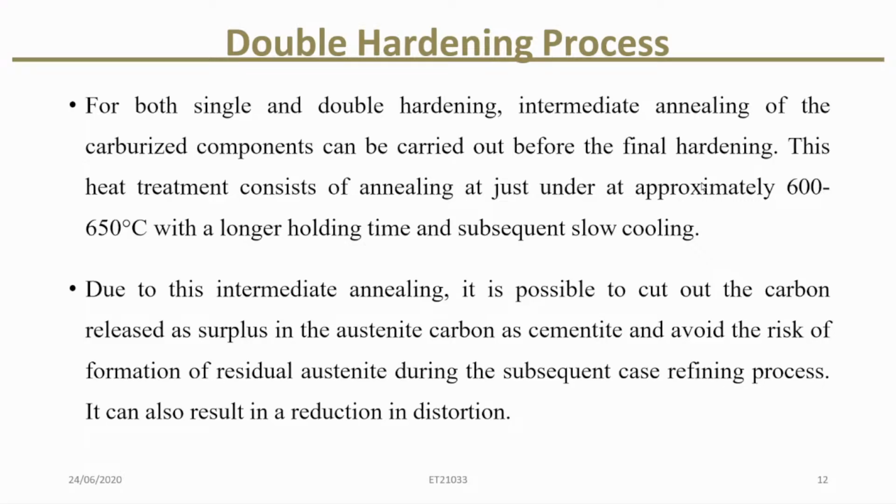In production, that translates to fewer size corrections after grinding and better gear tooth contact pattern. If you have ever chased size on a deep case gear, you know how valuable that stability is.